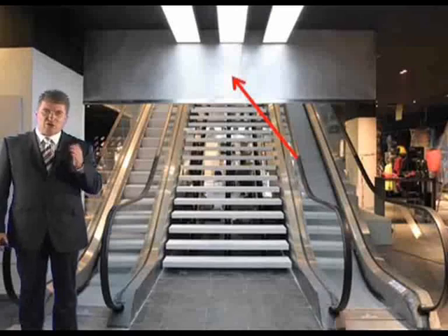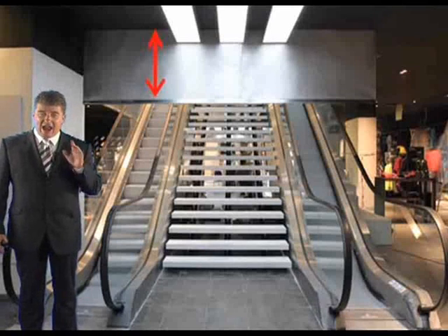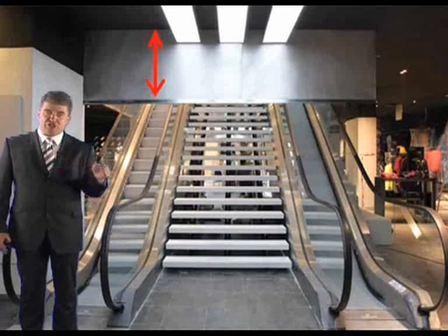Now, there are other essential factors that should be borne in mind when designing a smoke control system. When the mall has more than one level, it's also necessary to restrict or channel smoke on the lower levels in order to restrict entrainment into the plume rising through the upper level. For this, you've got your channeling screens. Once the smoke has entered a ceiling reservoir, it will flow towards the extraction points. Since this horizontal flow is driven by the gas's own buoyancy, there will be a minimum depth for any particular combination of smoke temperature and mass flow rate. Because it's using its own buoyancy, it's got to have a certain amount of temperature heating it to drive it out.